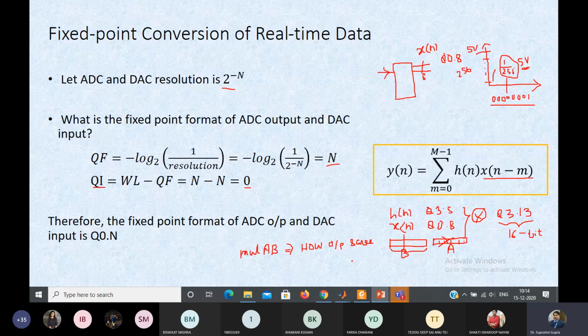Okay. And so after this MUL AB, if we want to transfer it to the port for the DAC, we need to move this content of B to A. Right? And then we can move it to, say, port 1 or port 2, wherever we are connecting our DAC, from this A, so that we can utilize it.